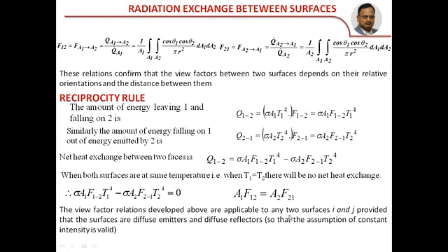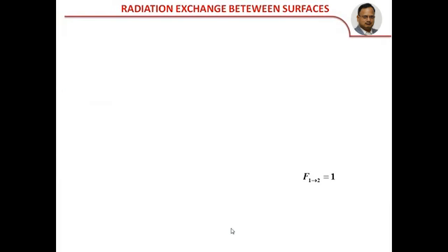The view factor relations developed above are applicable to any two surfaces, i and j, provided that the surfaces are diffuse emitters and diffuse reflectors, so that the constant intensity condition is valid.